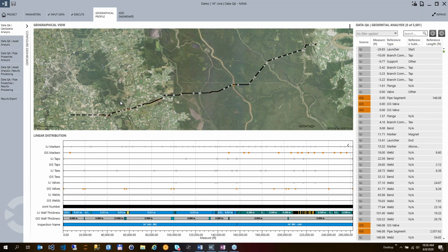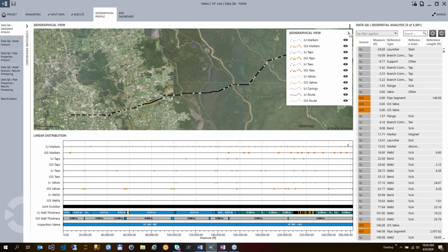So here what I have in front of you right now is a very basic map, because let's say that we did have our PODS database built 10 years ago, for example, using SBuild or whatever technology we had back in the day. But now we ran an inline inspection, meaning that we had a tool that ran through all this pipeline with a unit inside that actually got the coordinates, right? So we did plot what was identified in the inline inspection versus what we had in PODS.